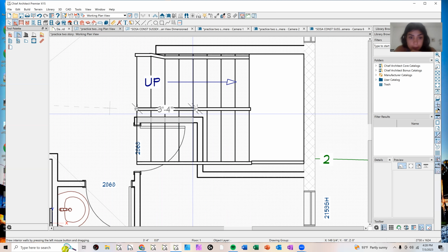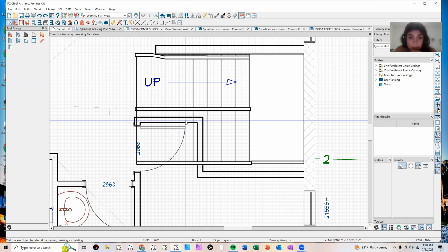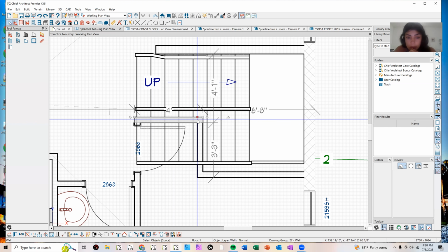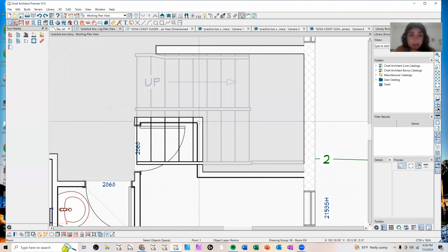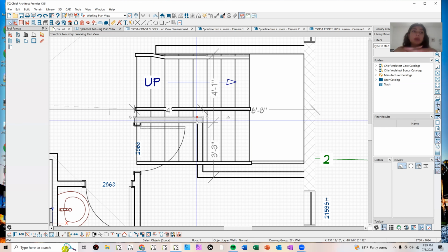Or you can make that wall, this wall, probably be easier to make this wall. See, the stairs are in the way. If you hit tab, you can get to the next layer. So I want to get to the wall. The stairs are in my way. Hit tab.